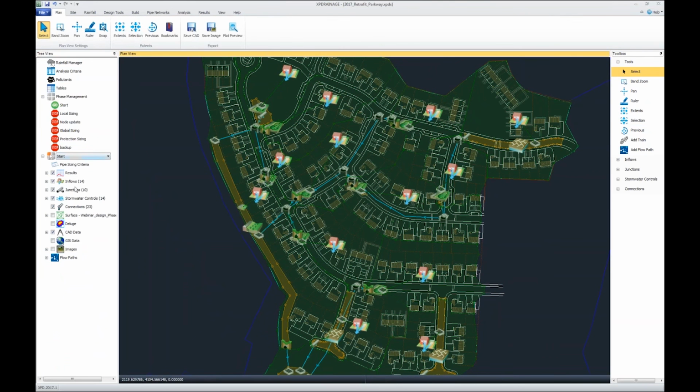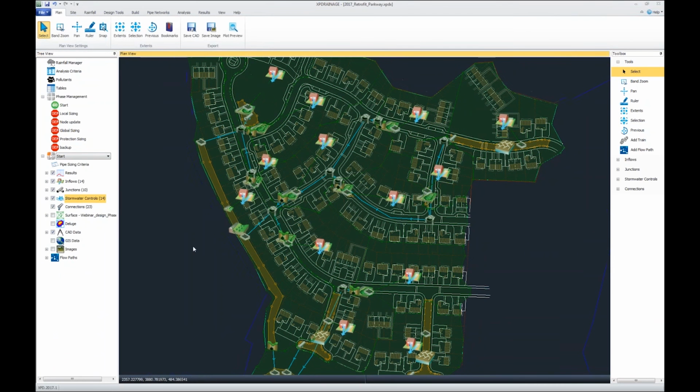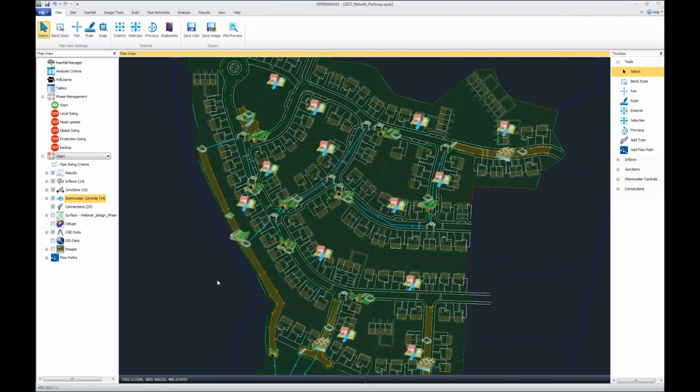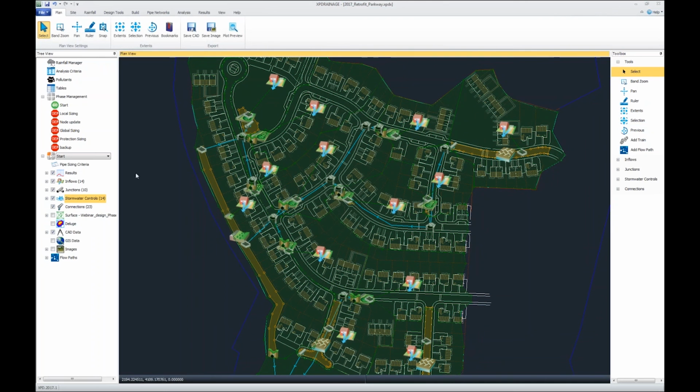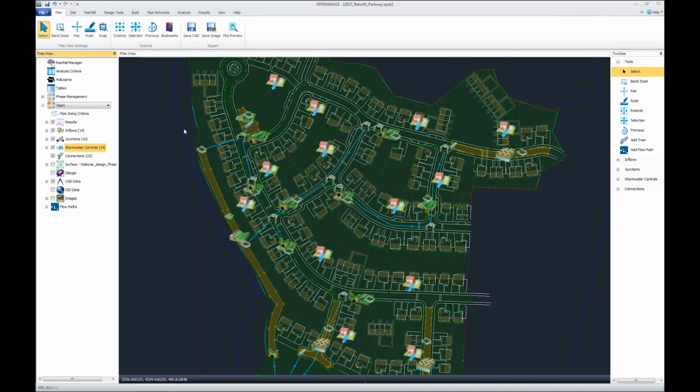I've shown a number of times in the past how we can right-click and import from CAD or GIS a range of items. What we found, talking to engineers, is that this next piece is, well, no matter what's done, the final grading plan, the work in CAD, is really cumbersome unless we give it some help, and that's what we did. So we can save this entire view out to CAD, so this whole plan view. So if we wanted to create the grading plan for the ponds, let's say, you can right-click and save this whole phase out to CAD.